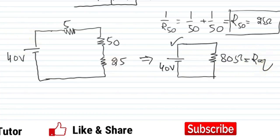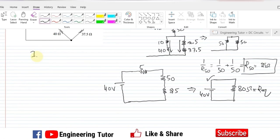Now we can easily find the value of the current provided by the 40 volt source, using Ohm's law. So I is equal to V by R. V is 40 divided by 80, so it is now 0.5 amperes.